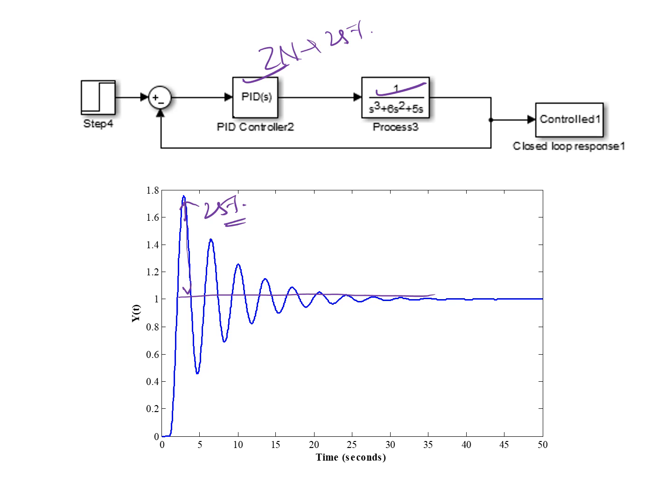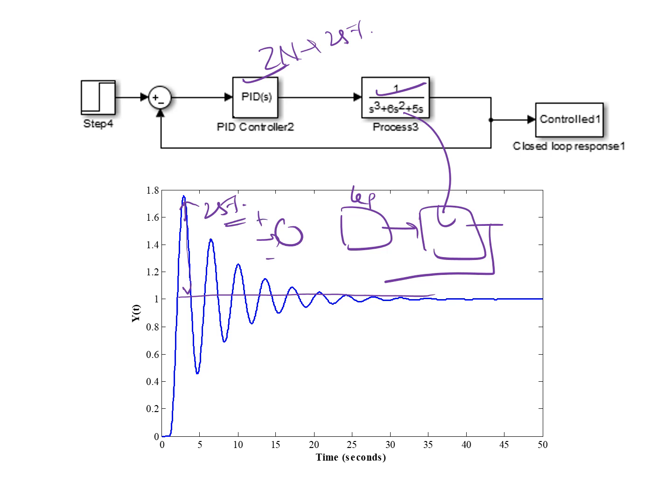Okay. So how to do the test? Just to recap. First connect this transfer function. Put the transfer function. Then you have to use the proportional controller Kp. Then connect this. So here you have an error detector. That's it. Okay. First start with different values. Start from 1 to 50.